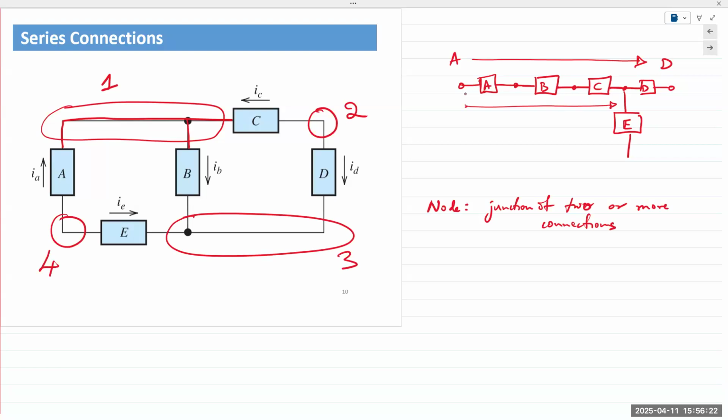Okay. Again, if you see multiple nodes in a circuit, the quickest and easiest way to identify is if you have anything connected between those two nodes. If there is no element except for a wire between those nodes, it is the exact same electrical node. Okay, it's no different. Right? So there are 4 nodes in the circuit.